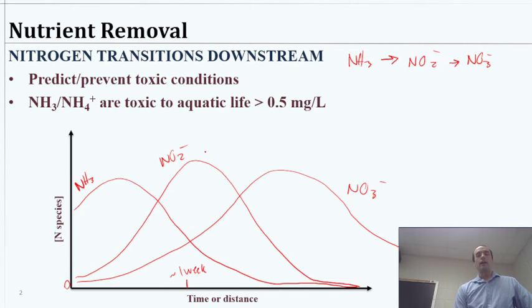Later on, now that you have a nice colony of nitrogen processing bacteria in there, it'll be happening more rapidly and more smoothly. We'll see the same type of function if we discharge organic nitrogen or ammonia. It'll still be going through that cycle downstream. Of course, it'll probably look a little different because there will be the bacteria there, but it's still going to take some time, and we'll see this evolution of the nitrogen species. Okay, so that's kind of an interesting thing.